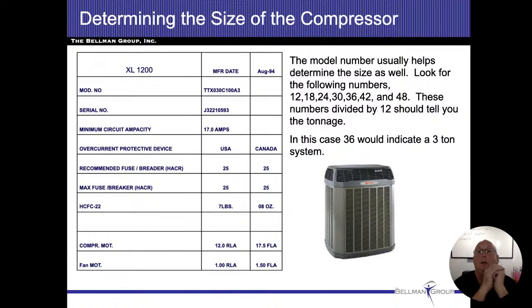And that's up there. So when you go there, what they did was they took every manufacturer and even the different years that the manufacturers did it, and they were able to decode all the different data plates that are on there. All right. But there's some things that you're going to have to kind of know so you can figure everything out. So in the model numbers, that's usually where they're going to hide the BTUs.